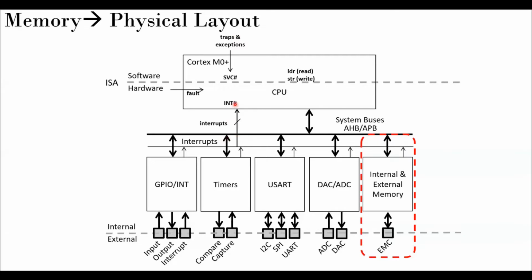Then we know that a CPU or a microprocessor is sort of a software controlled system. It's a serial system, of course. So you have to write the software in assembly language or C. And it is more of a load or store system, right? You have a memory, and from that memory the code which is written will be loaded into the CPU and executed. Based on that execution, different actions will happen. And the bus, the advanced system buses, whether advanced high performance bus or advanced peripheral bus, doesn't matter. Bus is a set of wires, in this case how many wires? Yes, 32 wires help you in moving the data from memory, from peripherals into registers, back to memory, and so on. So they are the essential nervous system in our computer system.